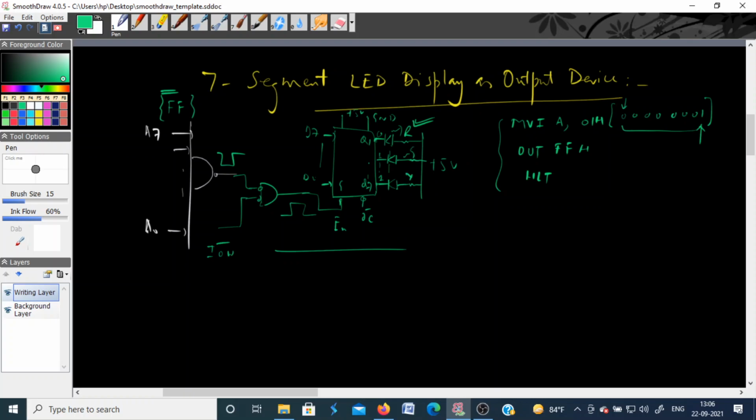So you can program the processor to turn on one LED for some time, then create a delay, turn on another LED for some time, and so on. In that case only 3 pins of the latch will be used, and the rest are not utilized. So you have to make sure that the data you are sending goes only on those 3 pins to which you have connected the light emitting diodes, right?